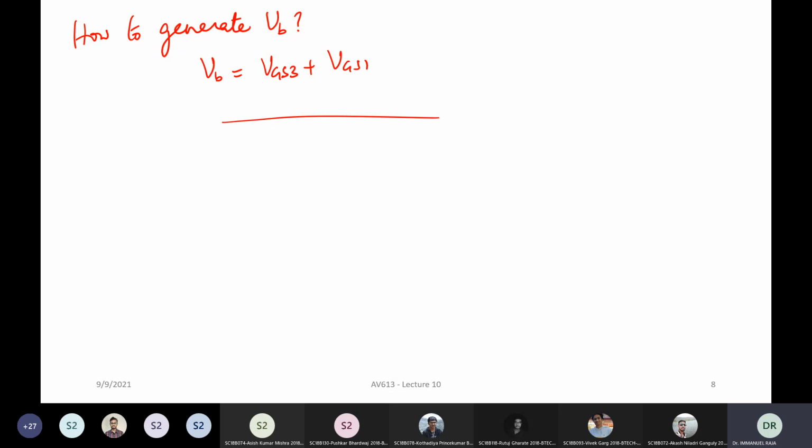Sometimes for deep submicron processes, the variations are so large that you can even put one of your transistors out of saturation. So that is a very bad thing, right? So you have to derive your bias voltages from currents without depending on the direct supply voltages.